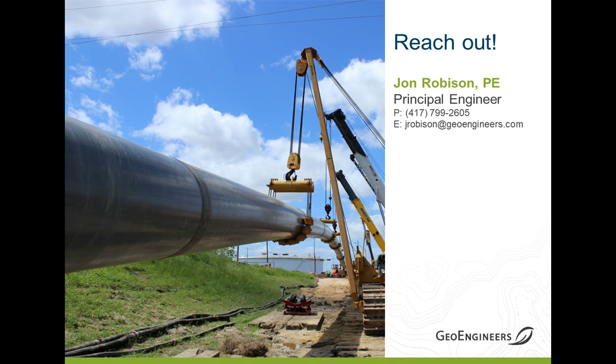And I think in that case, depending on how deep that obstruction was, perhaps you could dig a shaft and remove it. Perhaps you would have to pull your machine, retract the machine, and even grout the drilled hole in place, and then move over and start again.